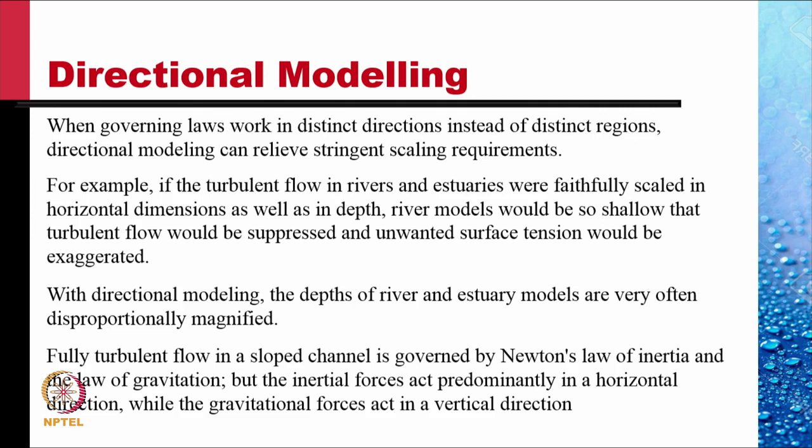With directional modeling, the depth of river and estuary models is very often disproportionately magnified. We use a smaller scale factor for the depth than for the length and width.